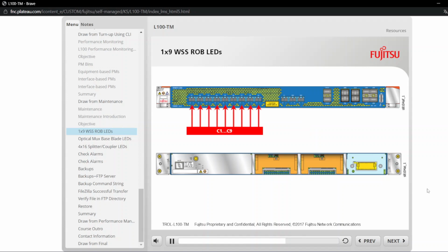C1 through C9 LEDs for client ports. Off: no power or unprovisioned. Green: incoming optical signal operating normally. Red: C1 through C9 port input down, or C1 through C9 port power out of specification. Fan 1 and Fan 2 LEDs, for fans. Off: no power. Green: normal operation. Red: equipment fault, a fan failed or was removed. Blinking red: fan mismatch. Loss of LED activity may indicate that the PIU is in reinitialization mode, operator activity, and not necessarily out of service, OOS.